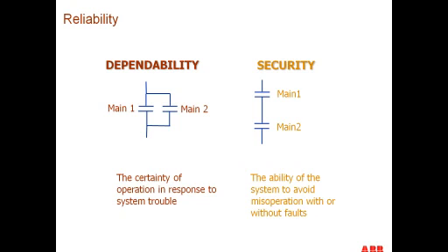Another question came in: do we need the same AC and DC supply for the breaker and relay? Ideally you would have a different DC supply for the breaker and the relay. But from the practical aspect, you really can't do that because of economics. So oftentimes you'll have the same DC supply going to the breaker and the relay, but they'll be fused separately, so that if anything happens to the relay, it will open up the fuse, and the breaker DC supply will still be maintained. So that's done either by using molded case DC breakers or using fuses on different circuits going from the DC breaker to the relay and the breaker. I hope that answers the question okay.